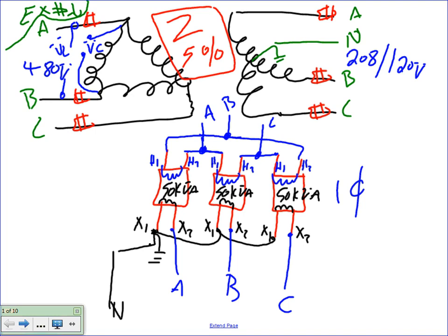Okay, any question guys about how this is physically connected. The top is the graphic, the schematic of it. Here's a delta, here's a Y. My system is 480. I'm bringing 480 on this side. So the line to line voltage is 480. The coil voltage, too.